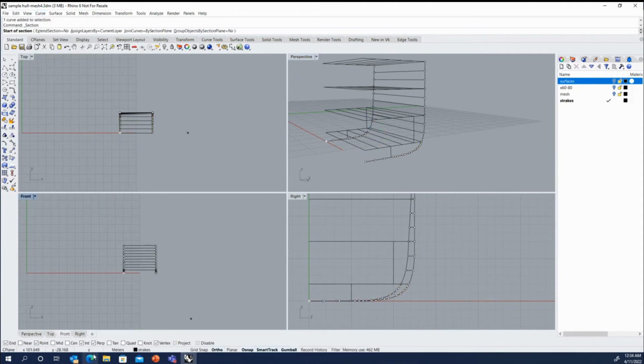Now, because I've got an end view here, I can't really see the locations of the endpoints that I want to select, but I can select them in this view and then trace it down in the body plan view. And you can see I got my points on either curve. So I'll go to the next one here, go straight down, go to that next one, go straight down. And I can use the end of this line to generate my other curve there.